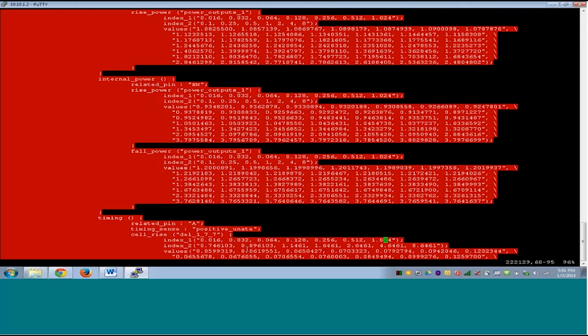So again the experience comes into the picture here. Now I know that a transition of 1 ns is very bad. We'll apply a clock of 2 nanoseconds, so we will synthesize the design at 500 MHz. When the clock itself is 500 MHz, a 1 nanosecond transition is very bad and will not occur. So we look for some realistic value.